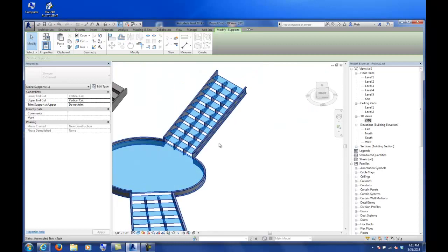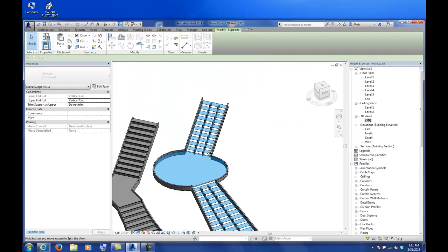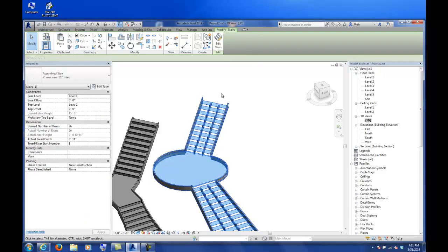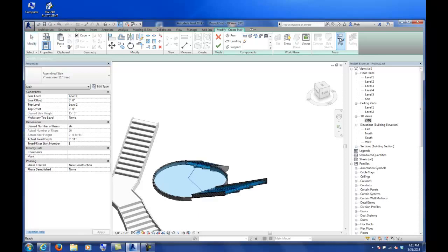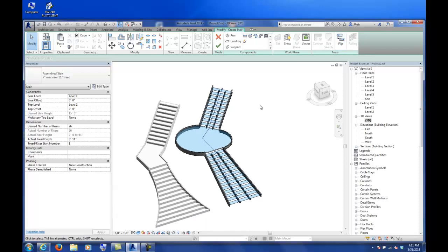Let's see, any questions about stairs right now? I accidentally flipped the directionality of the stairs. Uh-huh. Long run. How do I flip it back? So under edit stairs, there's usually this flip button that's over to the top right. You can just click that, it'll flip the direction of your stair. How do I do it for just one run? Oh, you just did it on one?